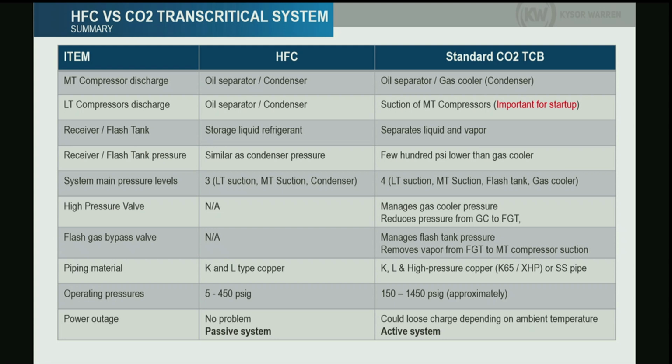We talk about the operating pressures. This is an important one: the power outage. What happens in an HFC system if we lose power? If we lose power in the store and you don't have power for 1 hour, 2 hours, even 1 day or 2 days, in your HFC system, nothing happens, right? You don't need to consider basically anything. Well, with CO2, it's not the case. CO2, as we said, has a very high coefficient of expansion, or expands really quickly. If we increase the temperature of CO2, it will increase the pressure.